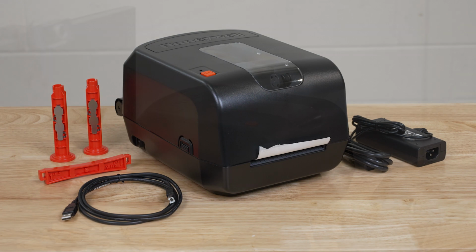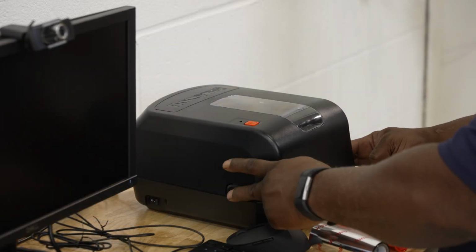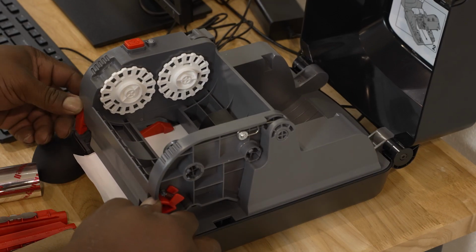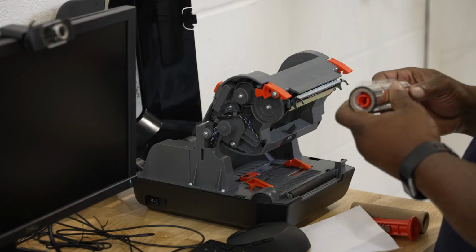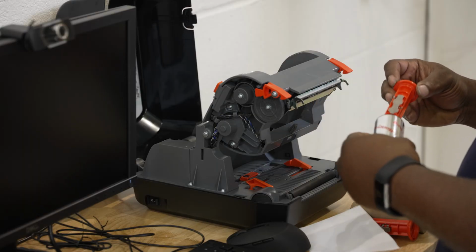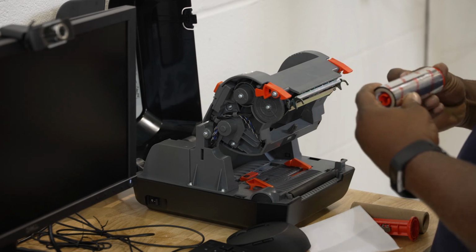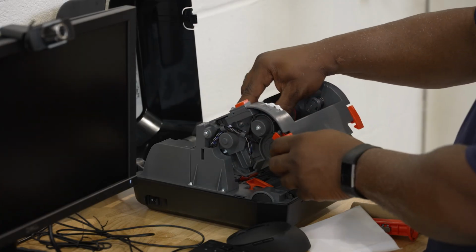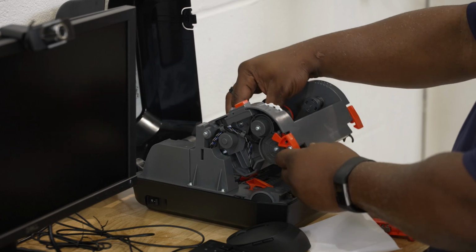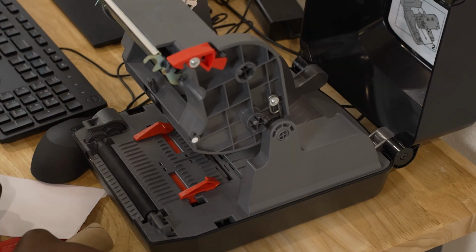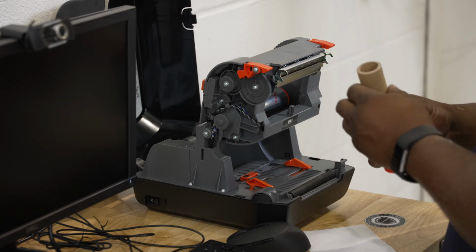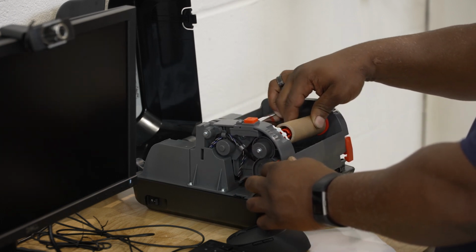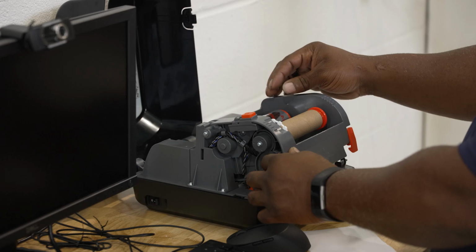To change the sticker printer ribbon, open the printer cover by pressing the latches on both sides of the front of the cover. Press in on the locking tabs to open the print and ribbon mechanism. Insert one of the ribbon adapters into the printer ribbon transfer roll. Make sure the ribbon feeds off the top of the roll so that it will be ink side facing out. Place the thermal transfer roll between the rear ribbon holders. Insert the other ribbon adapter into the empty ribbon take-up core. Place the empty ribbon take-up core between the front ribbon holders.